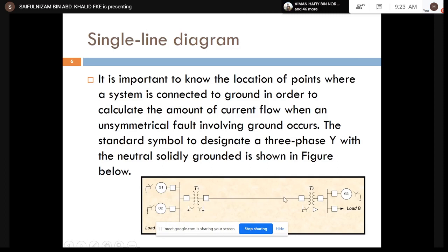And this is the transmission line, and this is transformer T2 with star solidly grounded on the primary and delta on the secondary. This is the bus bar, both at the sending and the receiving end, that connects all the components. And this is the circuit breaker, the G3 synchronous generator, and the neutral earthing of G3 through impedance.